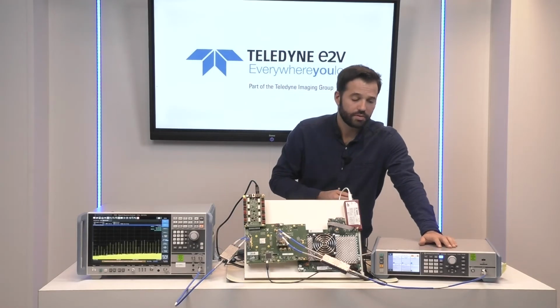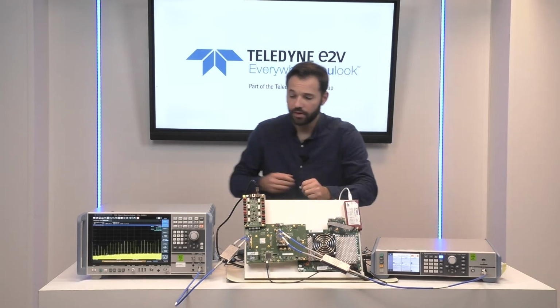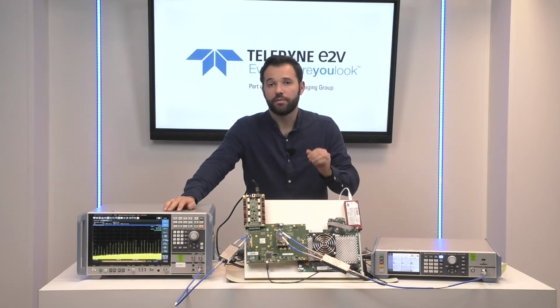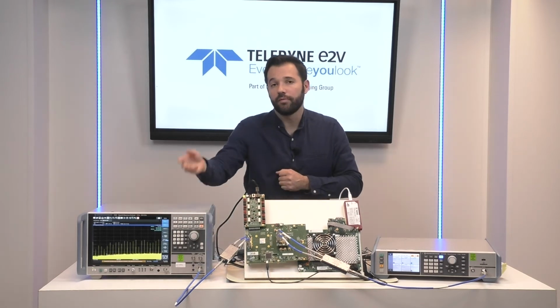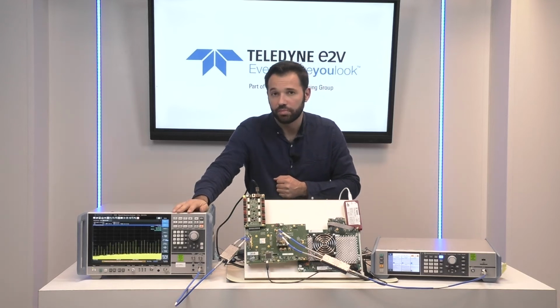We also use a signal generator to generate the DAC input clock and the spectrum analyzer to monitor directly the DAC channel B RF output. There is only here a balun to convert the differential output to the spectrum analyzer single-ended input.